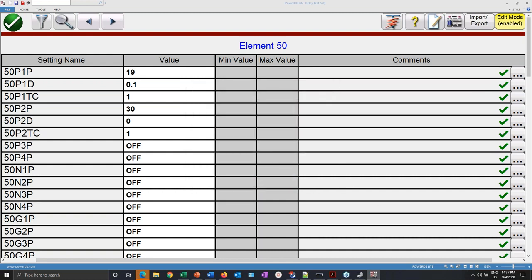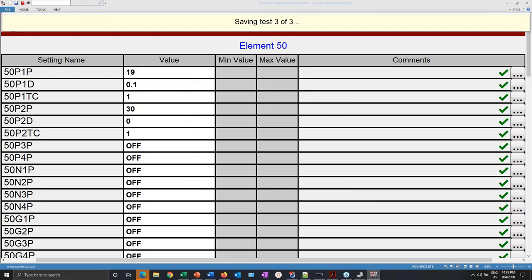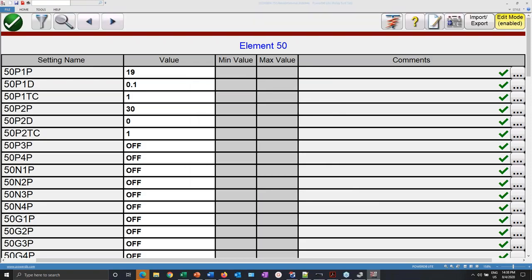Okay, you can reuse it. You can change the names and whatnot. You can test the same relay several times. Let's say you have to test the same relay every 2-3 years. You can reuse the same test sheet to test the same relay. Once you create this automation, you can apply it to as many relays as you want. Typically, the settings that matter don't change the name over time, so you can use it over the different generations of the same type of relay.